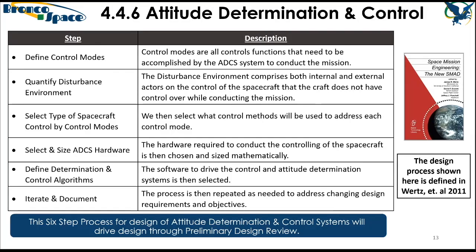In our case, we have these two solid walls, right? Like a six-sided cube, we had places to mount the magnetorquers solidly on 4 out of 6 sides. But in order to get all 3 axes, the 2 sides that we did not have somewhere stable to mount a rod to, we decided instead just to have the open air coil because we literally just glued it onto the wall with space glue. And that's a pretty sufficient way to get around that. Does that answer your question, Michael?